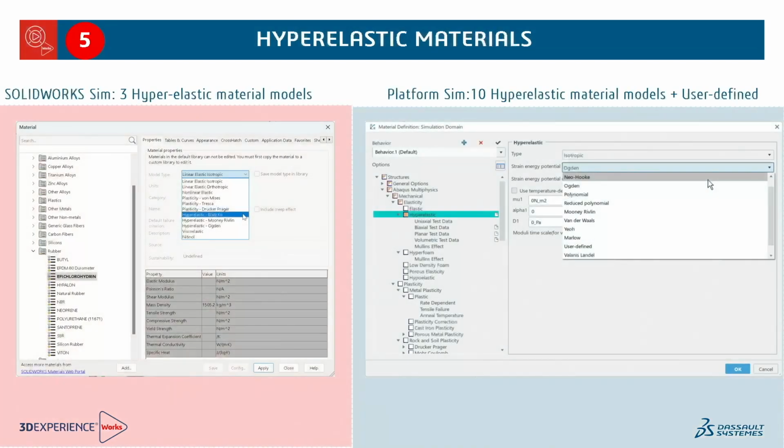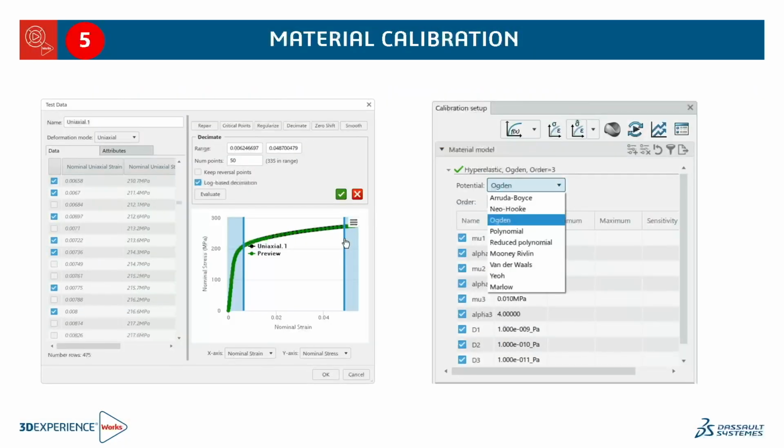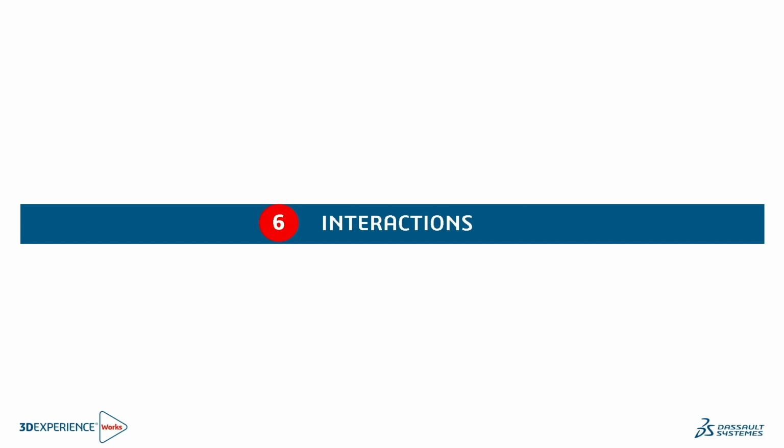And for this particular gear shifter of our fancy sports car, we need a rubber material. In SOLIDWORKS Simulation we have 3 hyperelastic material models, and on 3D Experience simulation we have 10 hyperelastic material models plus the user-defined one. And for those who have material data from some test lab, you can use the material calibration, which is powerful and widely used by a lot of users. And with that, I'm going to hand it back to...